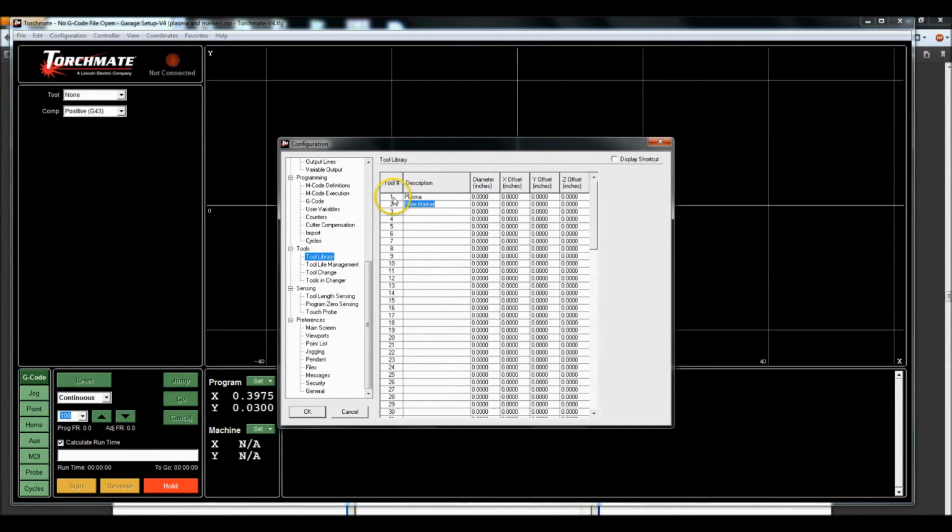Notice the tool number is 1 and 2. These are turret numbers in the CAD software, and so they correspond one with another, so don't mix those up. So make sure you have your turret numbers in your CAD software pointing to the right number here. So plasma and plate marker. Now I do everything designing inside of my house, and then I export it to a shared drive and connect outside to that shared drive, and then just run everything out on my machine out there.